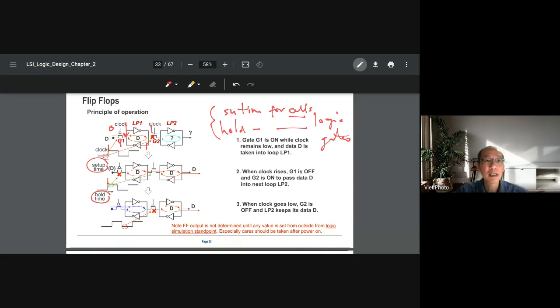In the circuit they do that. I see in the cell library they make these two gates not much, because they have positive feedback here, right? They make it just a minimum width of transistor. But this one would be a wider width for the transistor, so that they make it faster.